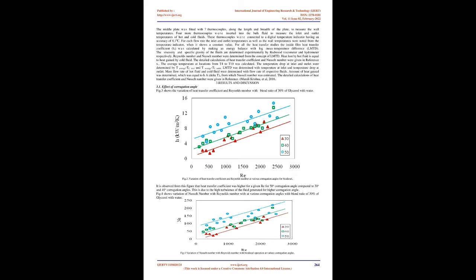corrugation angle. Carla S. Fernandes et al., 2008, studied laminar flows of Newtonian and power law fluids through cross-corrugated chevron-type PHEs in terms of the geometry of the channels. The plate's area enlargement factor was a typical 1.17, the corrugation angle varied between 30 degrees and 60 degrees, and the flow index behavior, n, between 0.25 and 1.